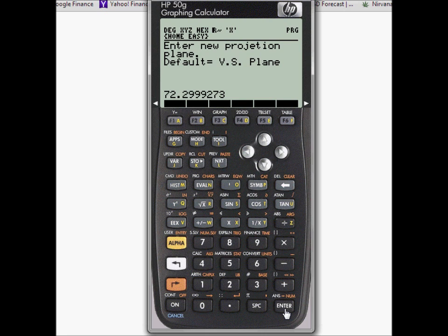So anyway, we can change, if we want, the plane along which the projection is made. In this case, we're not going to do that. And if we go straight rather than continue with a well direction at this point, that will incur an instantaneous 2D dog leg of 1.98. In other words, the well is going at 70.1, and we want to go to 72.3. So at nearly 70 degrees, that represents a dog leg of 1.98. So we accept it because we figure we can turn the well a couple of degrees to the right by the end we hit the target, so that's no problem.